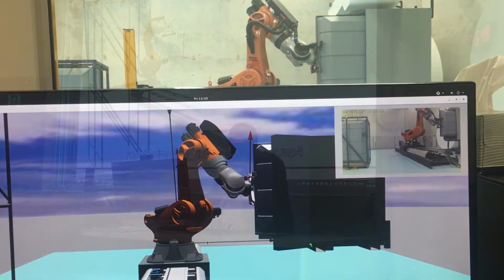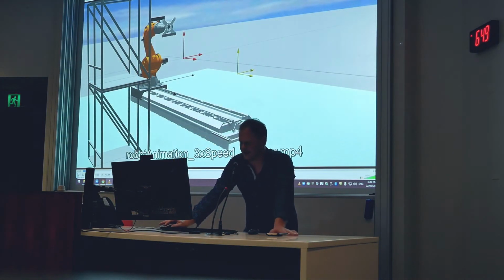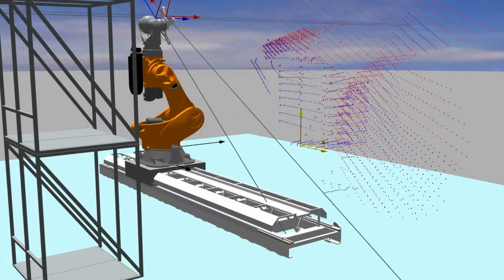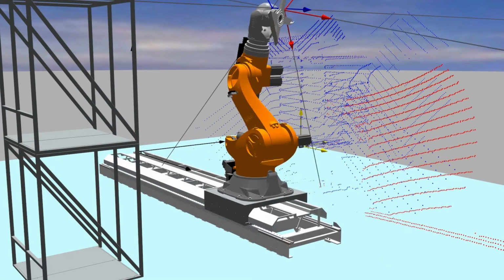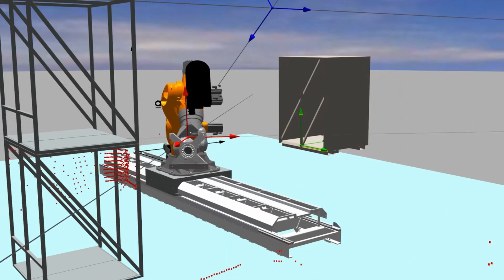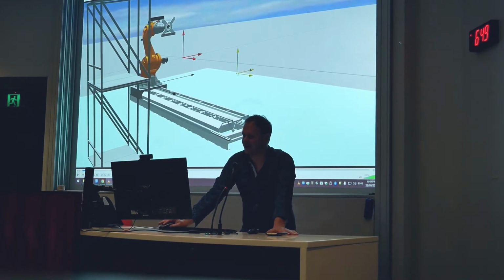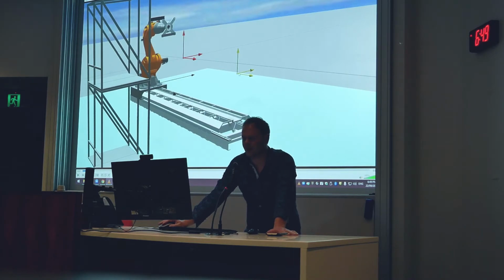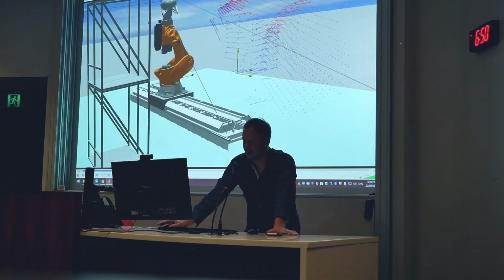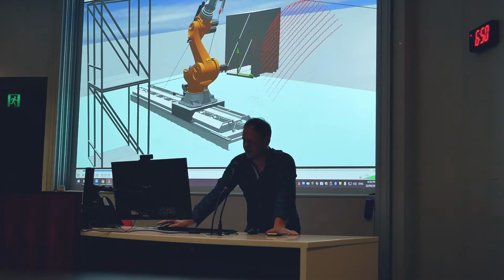But the one I wanted to show was maybe this one. This is the animation. So this is what it did at the start. It went, give me a scan, please. There's the LiDAR data. It took a scan there, and it took a scan there, and it says that's where it is. Found it. Just before that pops in, the yellow is, I'm not a good surveyor. I'll tell you that. I've surveyed where I think the truck is, the cradle is, that shape. I've surveyed that, and this is what I believe to be the truth. Roll pitch yaw, XYZ of that cradle. The green one that pops up on top of it is my estimate. So watch it do it again.